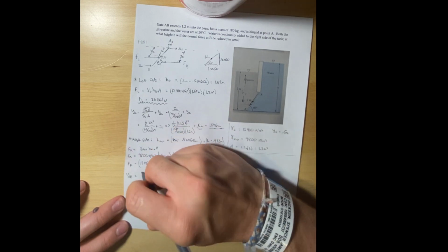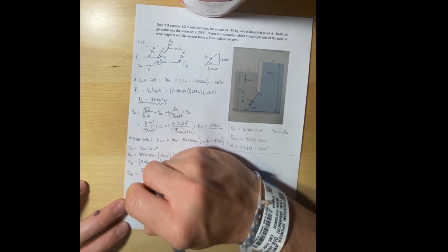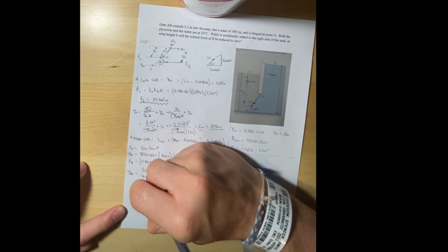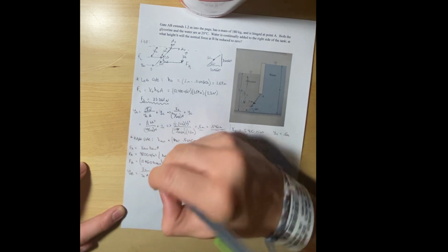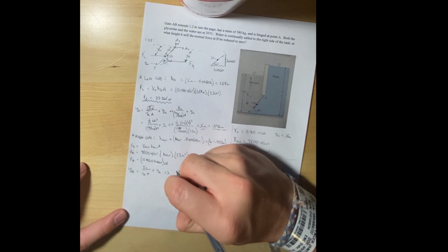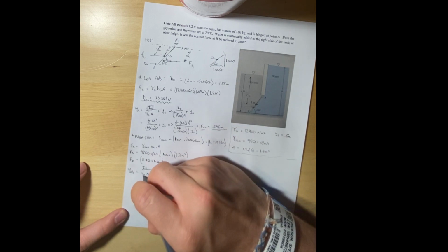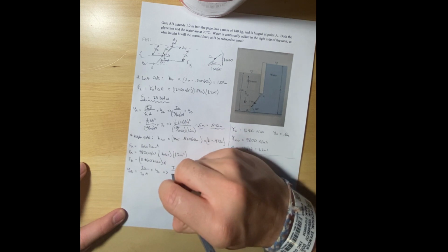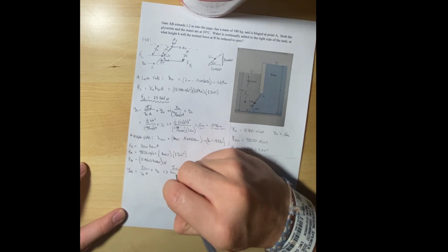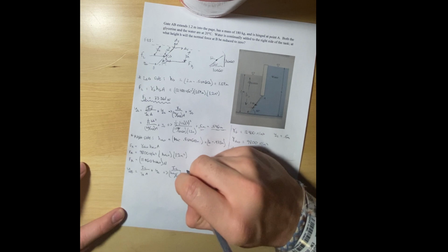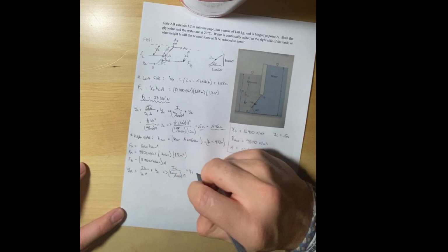And just like above, we're going to use the formula of the moment over our y sub r distance times A plus our y sub c term, which is then going to lead us into, we're going to sub this out for the h height, this time for water though, over sine 60 times the area plus our y sub c term.